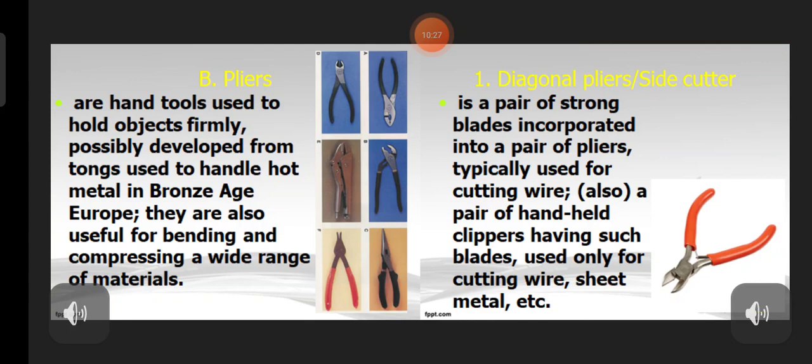Different pliers are helpful for different situations. Examples are combination pliers or slip joint pliers. These are the most common pliers used. The slip joints allow the jaws to be adjusted to grasp different size parts. Another example is rib joint pliers or channel lock pliers or water pump pliers. They open extra wide for holding very large objects. The needle nose pliers are excellent for handling extremely small parts or reaching into highly restricted areas.